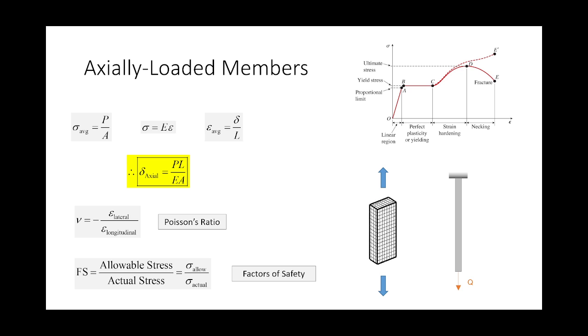They're solid in terms of their performance. If I go do a tensile test today on a piece of carbon steel, I will get essentially the same representative plot. Now, what we tend to do in most engineering applications is restrict our behavior towards this linear region. The reason why is because in that region, steel and many engineering materials exhibit this behavior,